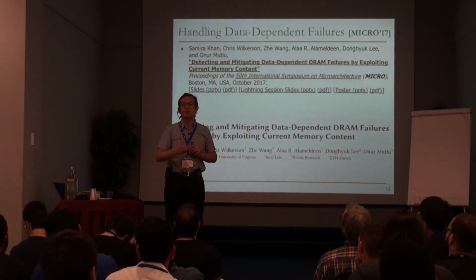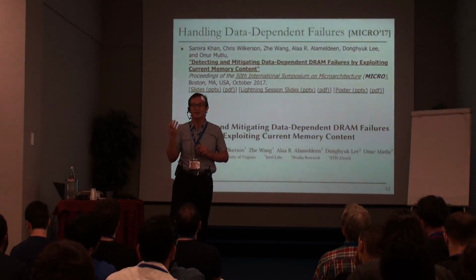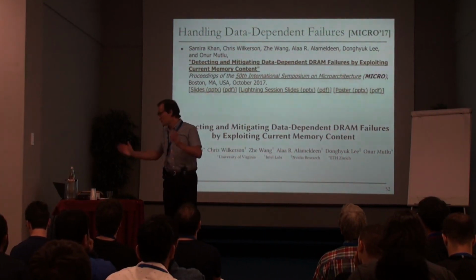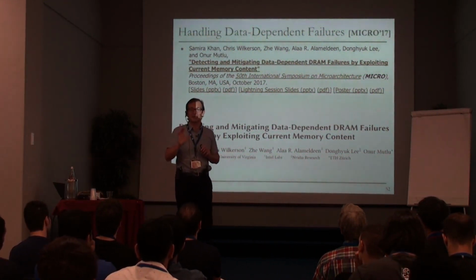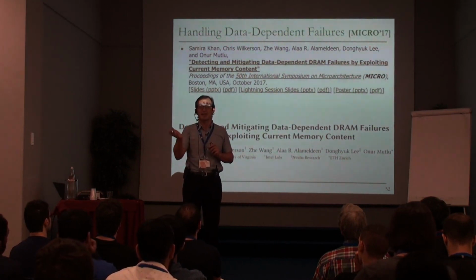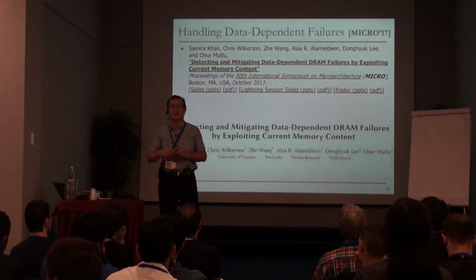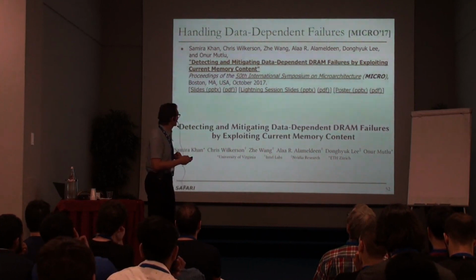So we're doing some of the tests online, but you need to be very intelligent about what tests you employ online because it has very severe implications on performance. So basically the vision is that the DRAM manufacturer doesn't identify all of the retention times because they're not able to. The system online identifies all the retention times and optimizes its behavior. And you need an intelligent memory controller to do that and optimize for the tests.